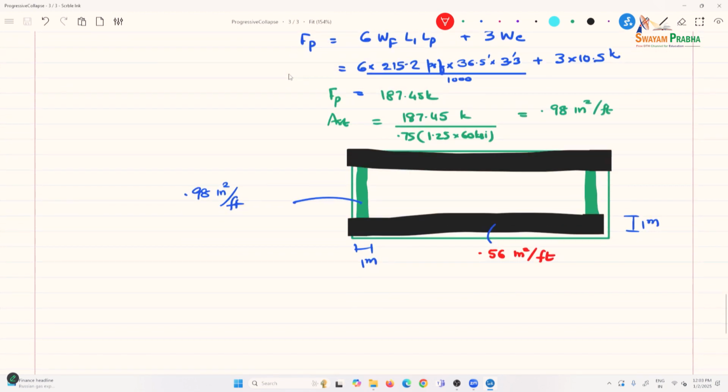You can ask the question, how about, are you going to overlap internal ties and the peripheral ties for the outer bay? You can provide the internal ties for the internal bay. So, if you are having here, of course, you have only one bay in that direction. So, the internal ties can be provided here and here. And here and here. You do not need to double the peripheral ties and the internal ties.